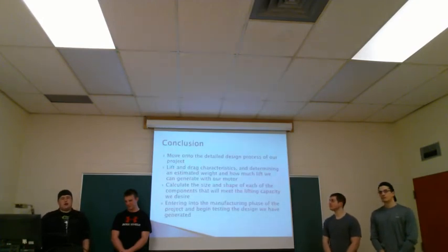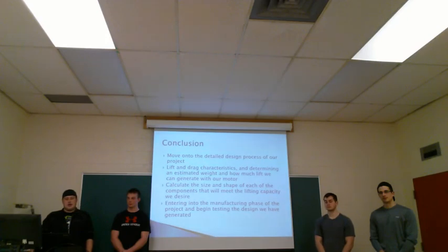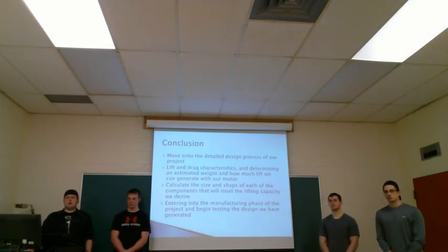So in conclusion, our next step is to move on to the detailed design process of our project. We have to determine our lift and drag characteristics and determine an estimated weight and how much lift we can generate with our motor. We need to calculate the size and shape of each of the components that will meet the lifting capacity that we desire. And we have to enter into the manufacturing phase of the project and begin testing the design we have generated.